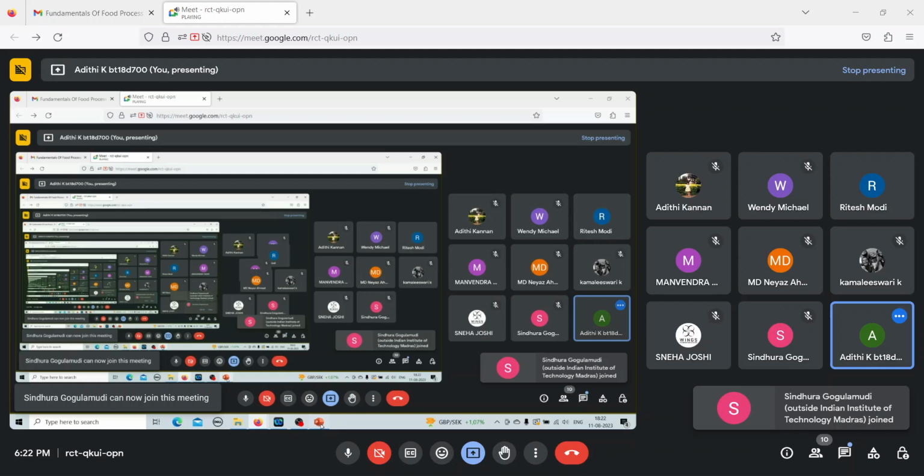Okay, moving to question 8. A food product is sterilized in a retort, which is basically like an autoclave where you maintain very high temperatures to sterilize the food. The time and the corresponding temperature in the center of the can are given in the below table. Calculate the F naught value if the Z value is 10 degrees Celsius. So here F naught value is basically at 121 degrees Celsius. The moment you have a naught, you're talking about 121 degrees Celsius. If the Z value is 10 degrees Celsius, F value is basically the time. So any clue how to proceed with this?